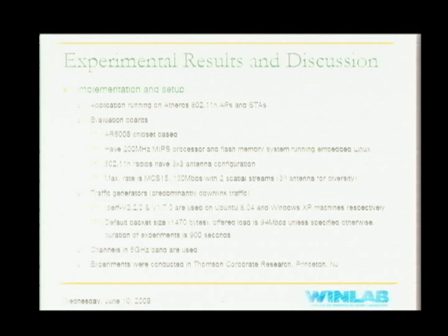And they also had a major drawback. These evaluation boards came with 100 Mbps Ethernet ports on them. Even though the wireless card is capable of greater than 100 Mbps transfers, the ports were 100 Mbps, so we pushed not more than 94 Mbps as our offered load. And that is the default offered load unless I specified otherwise. The duration of the experiments was 15 seconds each and they were all connected to the 5 gigahertz band.